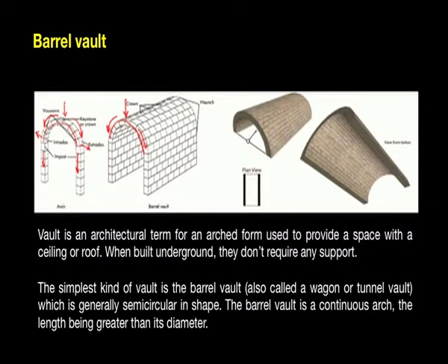The load is carried by all the voussoir stones on the sides, and again typically there is a vertical component, the main compressive load, and then there is a lateral component which occurs on the sides. This is again a thrust. This is what I told you about underground structures. When the vault is being constructed underground, the weight of the earth on the surrounding areas counteracts these loads so that the vault is kept in shape.